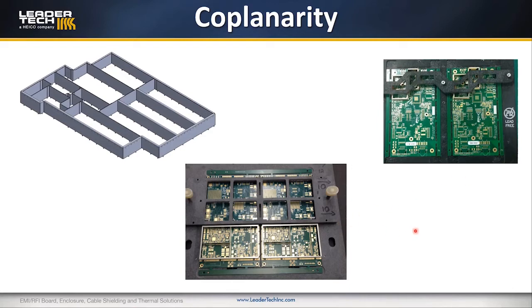These are also useful if you're soldering on both sides, so the shield would run through one cycle and then the board can be flipped over, and because of the fixture, the shield will stay in place as it's run through another round of reflow for components on the other side of the board.